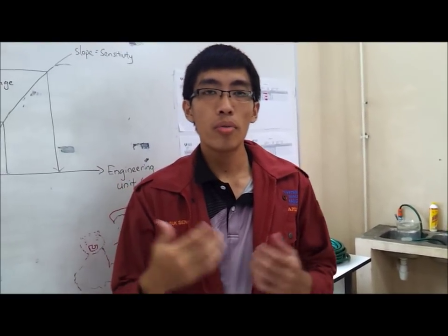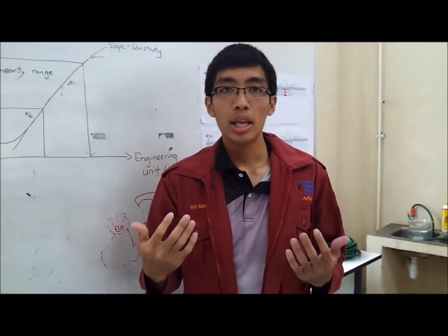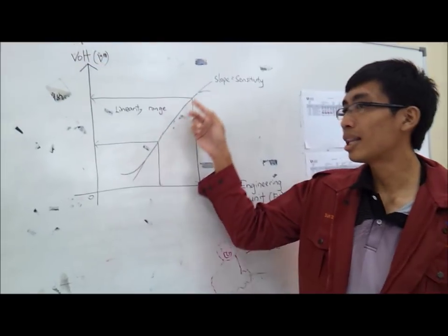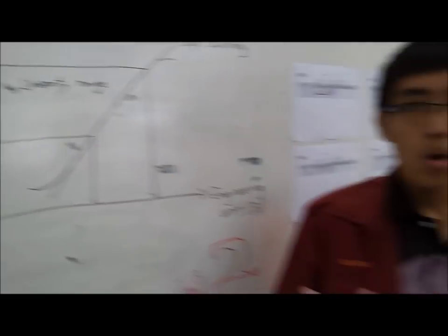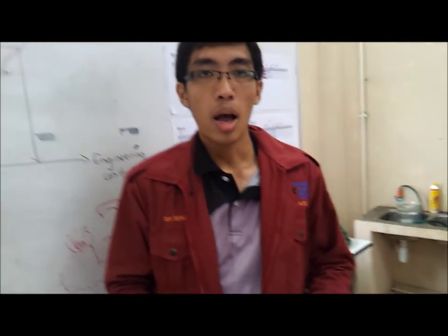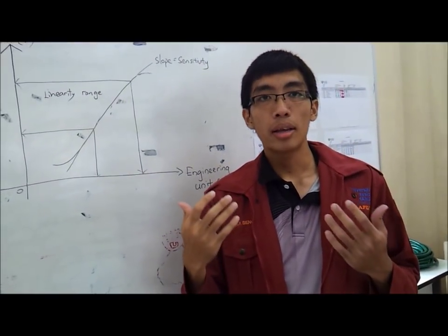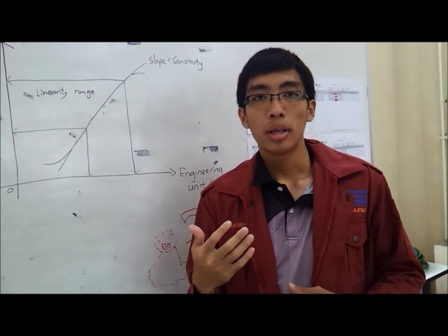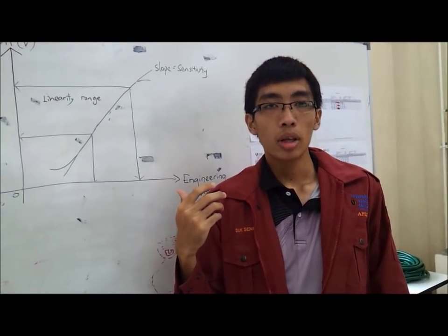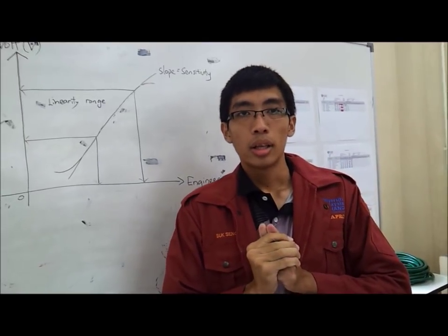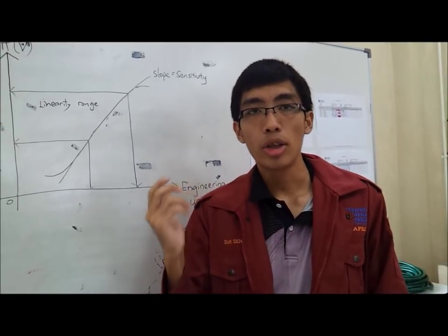But in the real world case, there will be a sensitivity error. There will be a departure from the characteristic slope. Like the example below, our sensor may have an actual sensitivity of 7.8 mV per volt per volumetric flow rate instead of 10 mV per volt per volumetric flow rate. So we can conclude that every sensor has its own sensitivity and operating range.